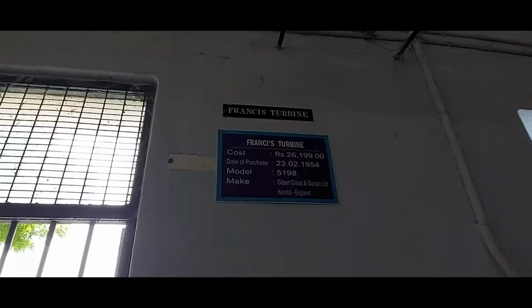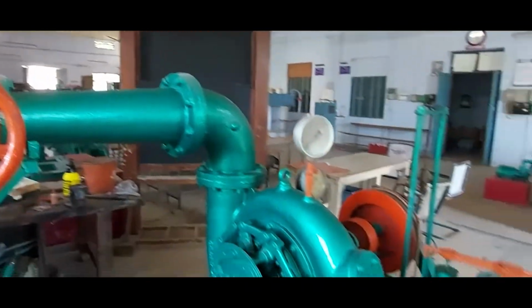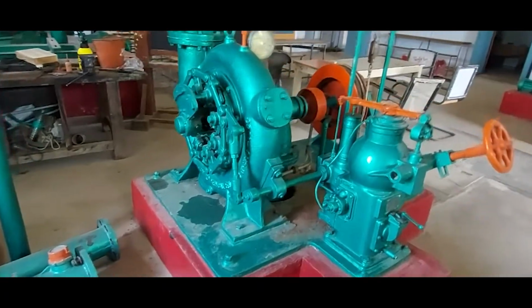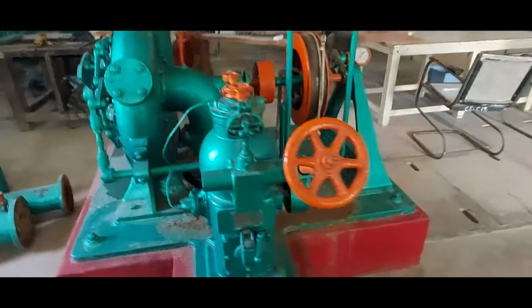This is Francis turbine. Francis turbine is a reaction turbine in which the fluid changes pressure as it moves through the turbine, giving up its energy. This experiment consists of penstock, impellers, casing, gate valves, spring balance, brake drum, etc.